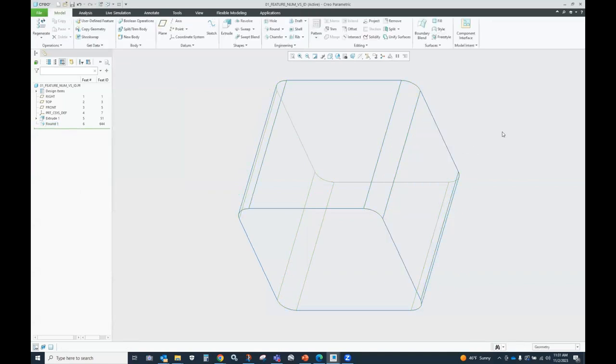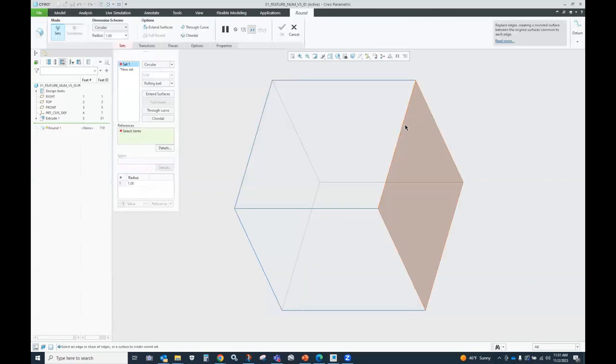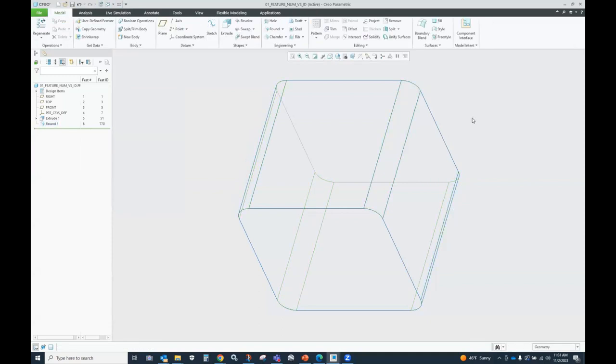Middle mouse button is finishing the round. So I can actually get very fast at creating these rounds, right? So I'm going to do it one more time: create the round, put my cursor there, tap right, pick middle, and all those rounds get created. Not only is it faster, but it's more robust. So the moral here is that control key is not always your friend. Sometimes you can't get around it, but look for other options that are more robust.